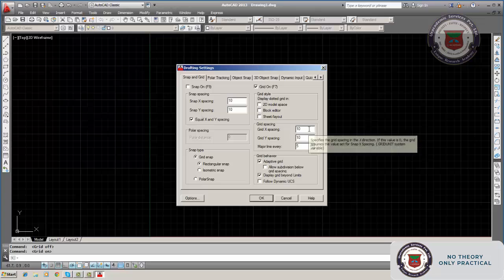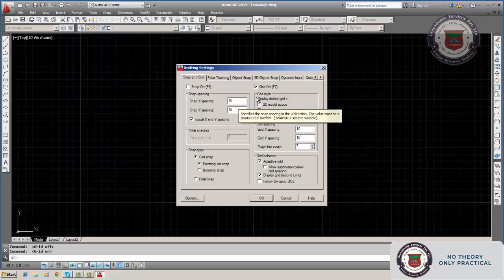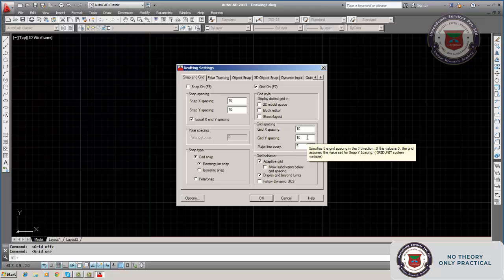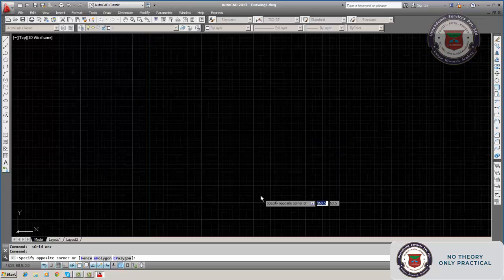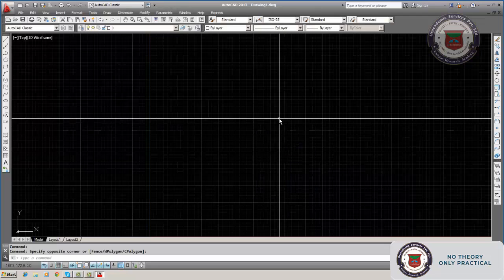The spacing is 10. Here also snap grid spacing is 10. Snap we will come to later on when we are talking about that portion. Don't get confused. We are discussing this portion, the grid spacing of 10. Why is grid spacing 10? You can change it to any different value. Automatically it changes to the different value. Click on this. Spacing is ready. Now it is 5 mm.